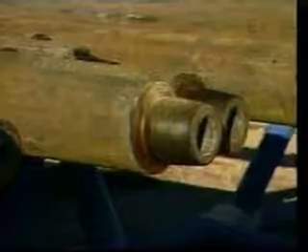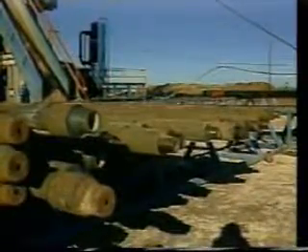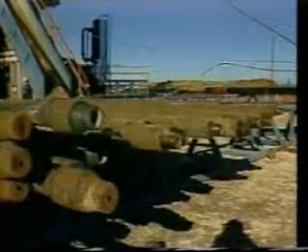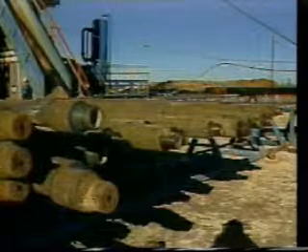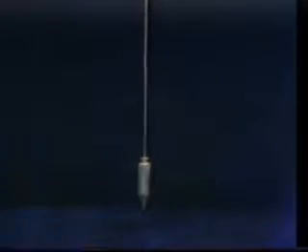The drill string is made up of lengths of steel pipe, drill pipe, to which are welded threaded pin and box ends. Similar to drill pipe, but having larger outside diameters and smaller inside diameters, are joints of pipe called drill collars. The heavy drill collars are used at the bottom of the drill string to hold the pipe in tension and prevent it from buckling, a problem which doesn't seem possible when looking at these pipe joints stacked here, but imagine them joined together to form a flexible string, a mile or two long, dangling down the borehole. If we try to put weight on the bit from the surface, the string will buckle. But by adding the weight on the bottom with the drill collars, a pendulum effect keeps the pipe in tension while we drill ahead.